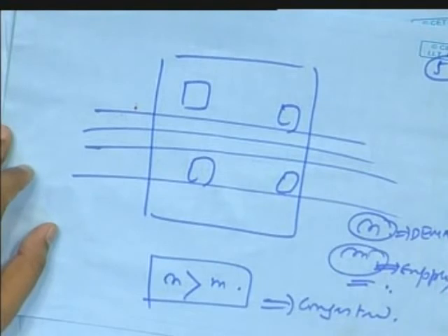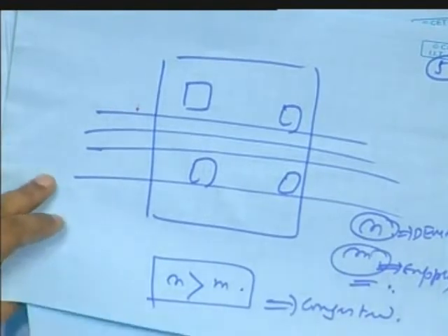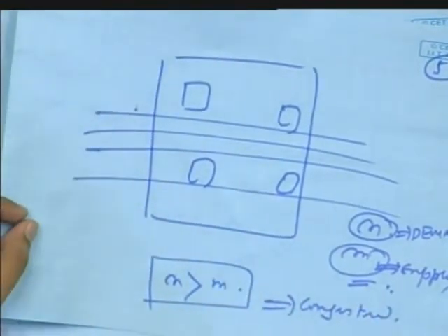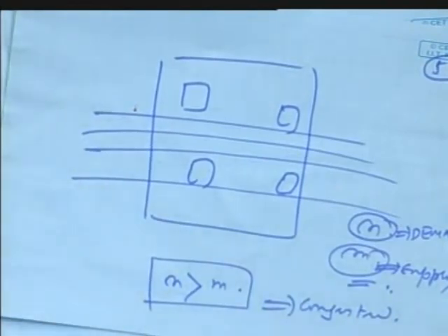This congestion removal is pretty huge. For our chip, I had seen the congestion removal of the Viterbi sequence detector. It took 2 months just to remove the congestion and fit in the existing footprint. If you relax the footprint and increase the chip, then the other company who is buying your chip won't buy it, but you can sleep well, right? Otherwise, you can understand, if there is a loop, you cannot place those loops far away, right? So you have to keep that in mind also.